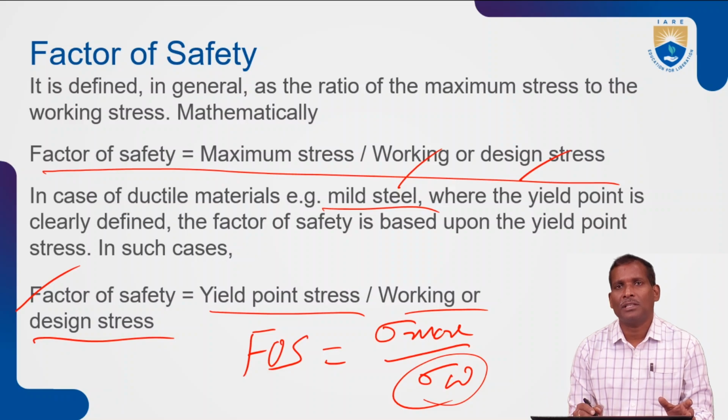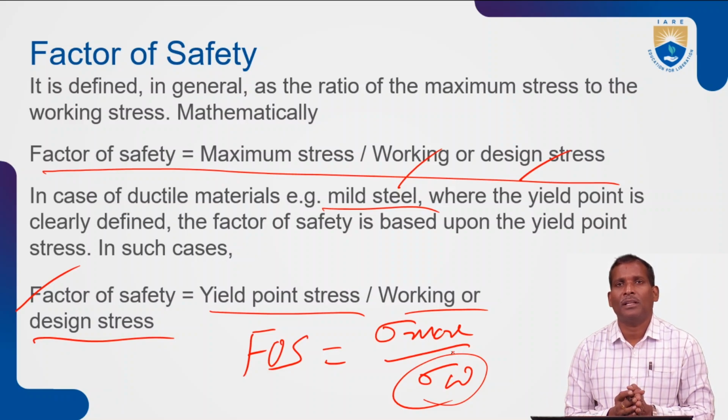The maximum stress means the material can withstand up to this stress value. So the applied or working stress is always less than this maximum stress for safe design. That's why you should take a proper value of the factor of safety for the proper application to avoid failure. For safe design, the factor of safety is very important in designing.